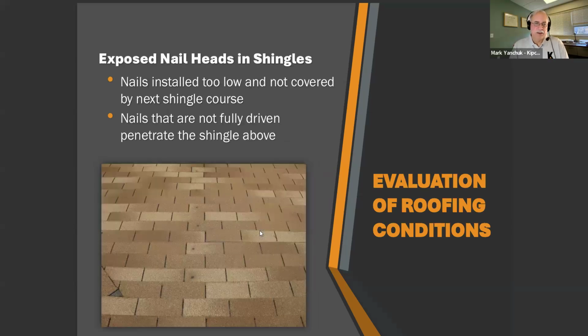Another example here is you might see a line of nail penetrations. A lot of times this might be an area where the nails were not fully set, and with the humidity changes and the swelling of the plywood going up and down, because plywood will move, buildings do move depending on temperature and humidity, the nail heads have worn through the shingles. Sometimes these may be seams in panels where the nail missed and is not even holding into any plywood.